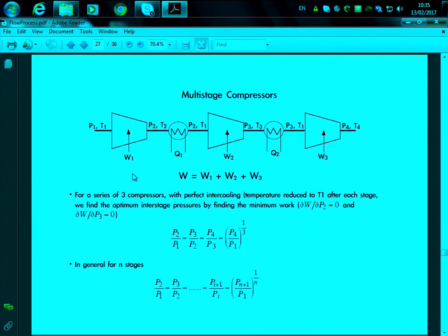So what we actually do is input this type of equations into a software system and compare the use of 1 compressor to the use of 2 compressors, 2 to 3, and we plot cost against efficiency. Okay, and then we obtain a place where the 2 values cross, where we obtain the number of compressors that we need in order to get the best cost benefit and the best efficiency of the system.